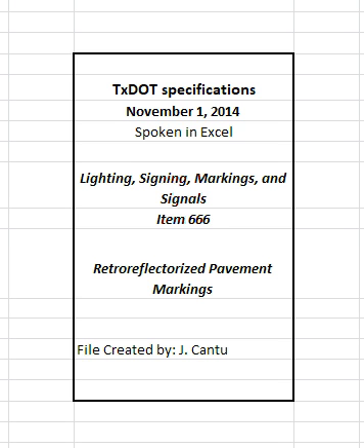The bead dispenser must have an automatic cut-off control, synchronized with the cut-off of the pavement marking equipment. Use equipment that has an automatic cut-off device with manual operating capabilities to provide clean, square marking ends, is capable of producing the types and shapes of profiles specified, and can provide continuous mixing and agitation of the pavement marking material.